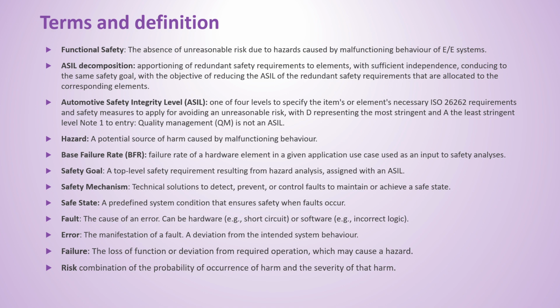The initial problem. Right. That fault can then lead to an error. The error is the manifestation, the system deviating from what it's supposed to do. So the faulty sensor sends a slightly wrong signal, maybe. The system acting weird because of the fault? Exactly. And that error, if it's not caught or corrected, could then lead to a failure. That's the loss of the intended function, or behaving in a way that might cause a hazard, like unintended acceleration because of that sensor error. Got it. Error causes potential failure, which leads to the hazard, and this all ties into risk.